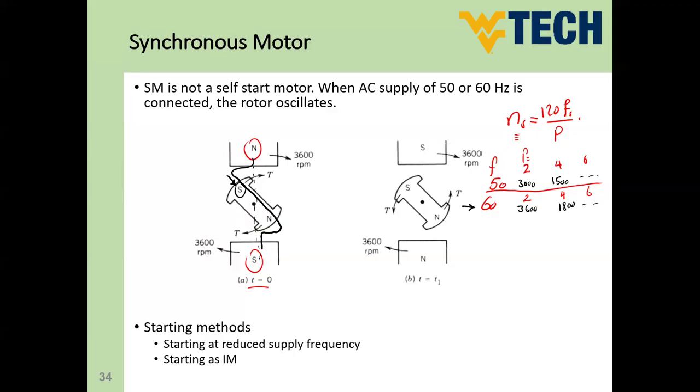If you have a motor, let me describe it when you turn off the motor supply. The motor is not going to stop immediately. It will take some time to stop because there is stored energy inside the machine, and this stored energy needs to be dissipated until the motor stops. So this is called the time constant, or mechanical time constant.